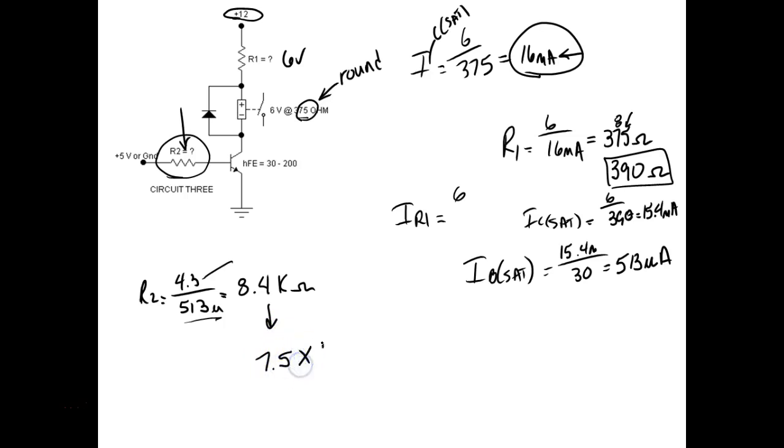Then we'll come up and just multiply that by 1.05 just to verify. So we're fine. So 7.5K is the one we'll use. So that's guaranteed, right? You understand? But we come back and we check the tolerance, right? Even though if you use that resistor, odds are it will work, but it won't be guaranteed, right?